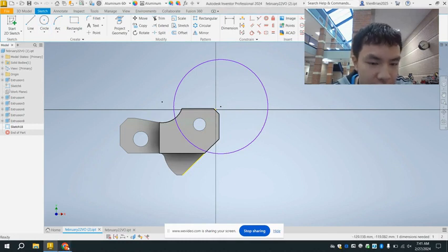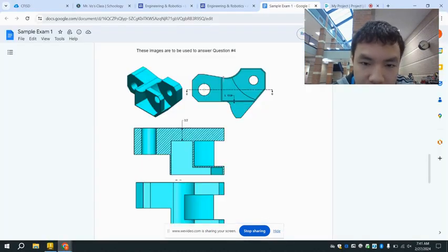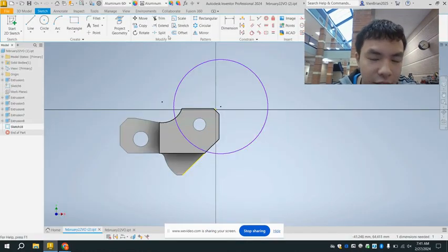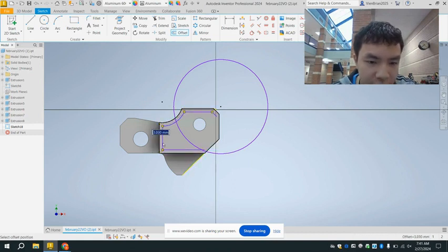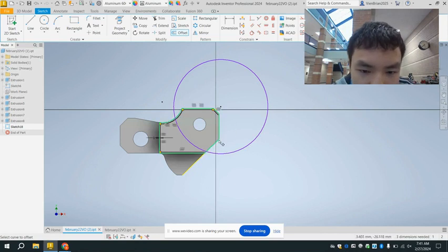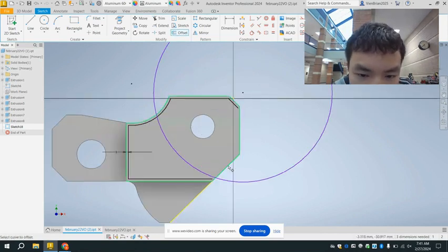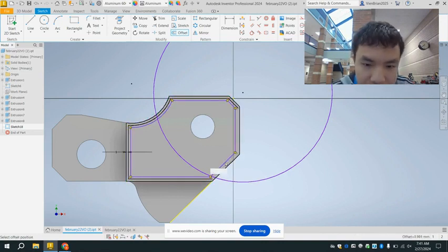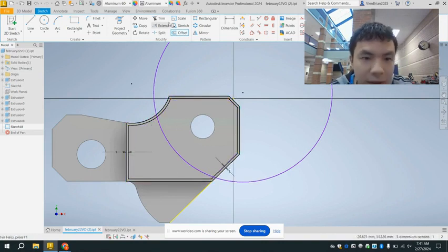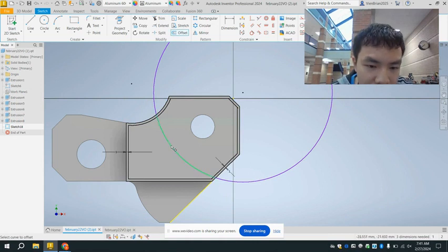And now you see how everything has a thickness of 1, right? 1 right here, everywhere. So in order to get that thickness of 1, you just press offset, and make sure, if this is like everything, you just do it individually. So right here, it goes to 1. And since this part didn't extrude, just offset that as well. Okay, it does that now. Offset. So now everything's offset. And this one you also have to offset by 1.